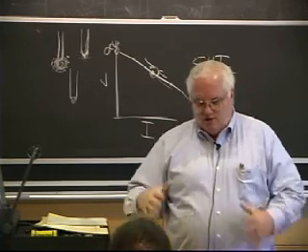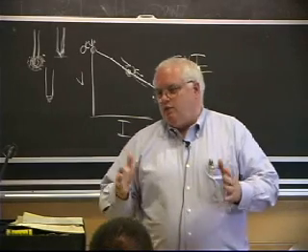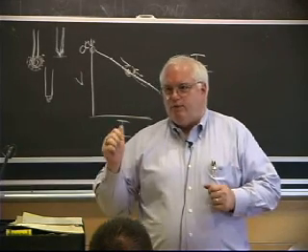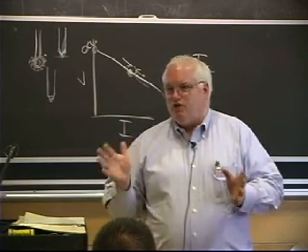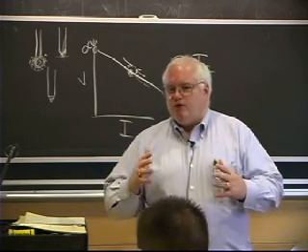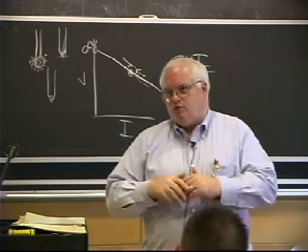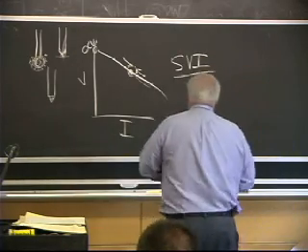You got to have enough turns, and this thing was a big heavy inductor. And with the new electronic power supplies, they basically program in the inductance. Okay, it's artificial inductance. It's not true inductance of stored magnetic field, but the program won't let you change the current but so fast. Okay, so you don't want to change the current too rapidly.